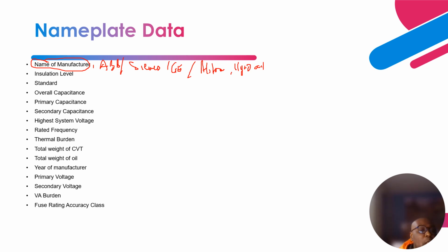So, the insulation level. Basically, we have the RMS and the peak. The RMS is the power frequency voltage. You can have a power frequency over voltage condition due to a ferroresonance phenomenon, and I explained what a ferroresonance phenomenon looks like.